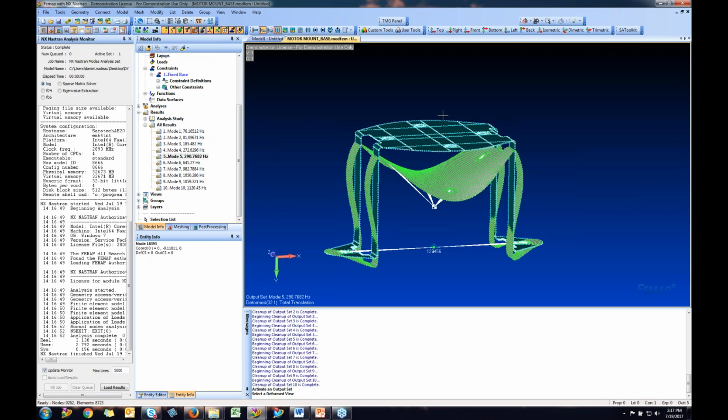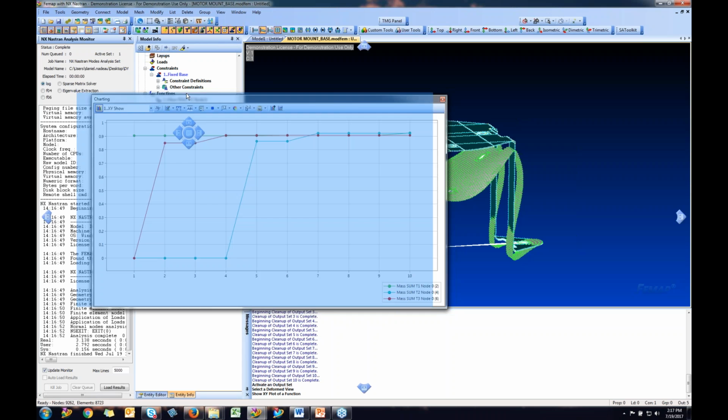So you can see the structure is moving in the y direction, so this mass has a lot of motion in here. So I requested out these mass fractions and the sum. So I'm going to visually plot this effective mass here. You can just select what you want, right click and show, and it'll bring it to the charting plane.